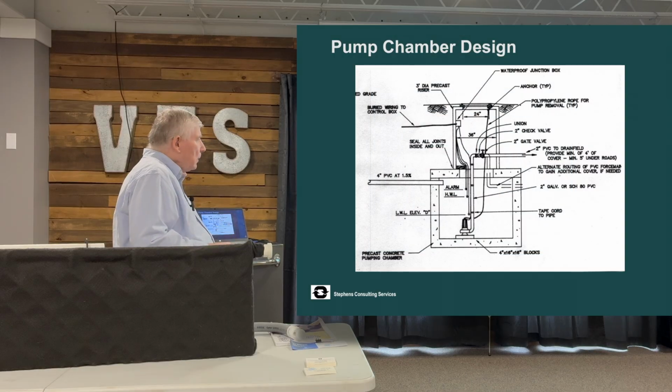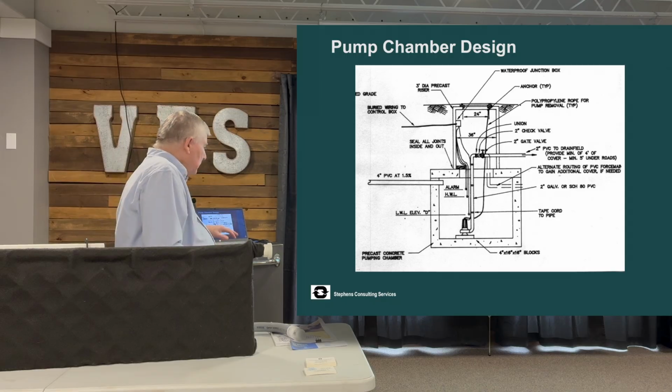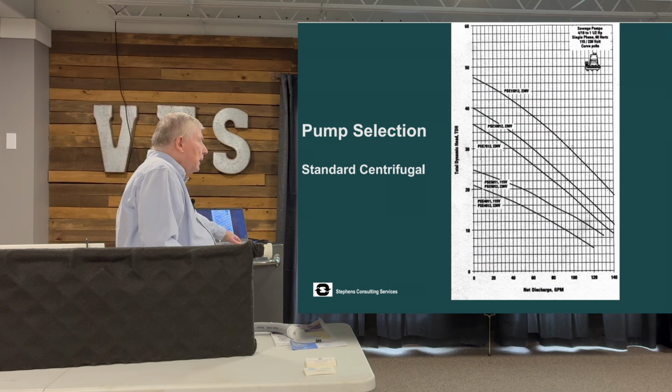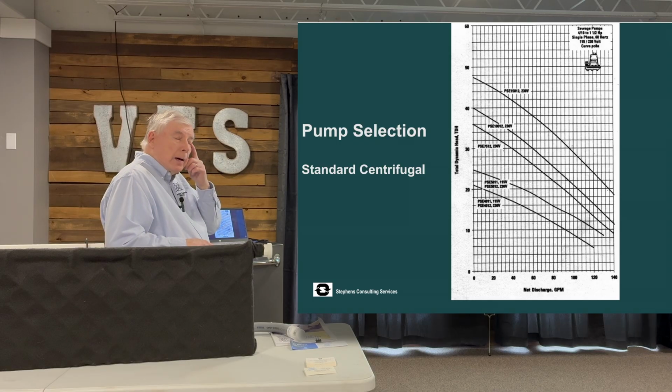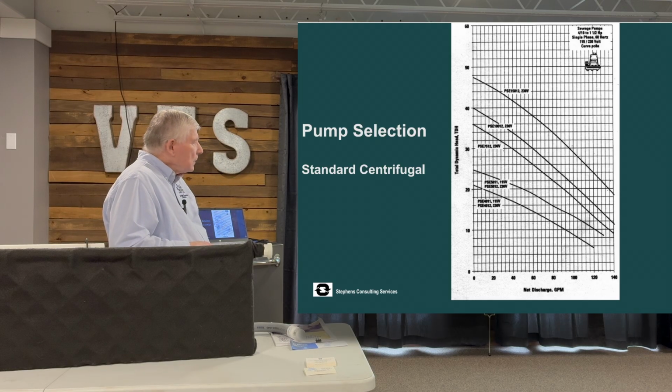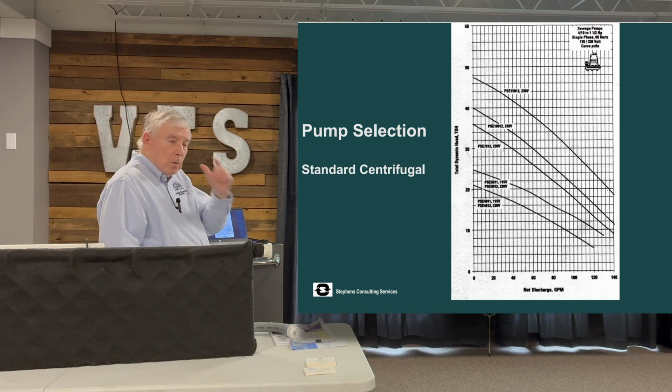So I never use this kind of design anymore, even though most health departments would approve it and expect it as a standard. But here's a lower head single stage pump, which normally sets on the bottom of a tank. And notice the cutoff head on these. Even the most powerful of those, the largest of those, the cutoff head's lower than 50 feet.